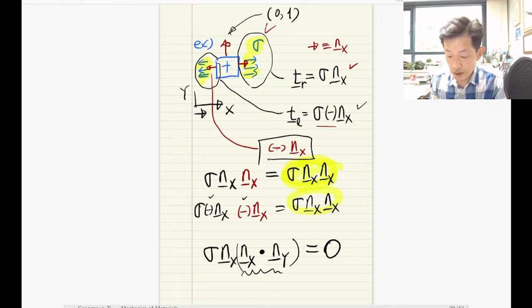And if you read the stress state in the x direction, in this case, then we have the maximum value. So in the concept of principal stresses, we'd like to find out the direction where we have the maximum value of the traction, and then we want to find out the magnitude of the traction. That's what we want to discuss regarding